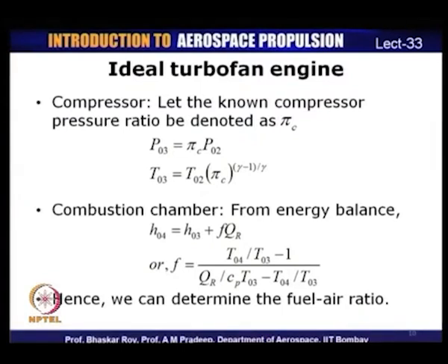And now, we move on to the combustion chamber. Combustion chamber analysis is something you are already familiar with; we did that in the turbojet. What we do is carry out an energy balance across the combustion chamber. At the inlet we have conditions of pressure and temperature coming from the compressor, then fuel is added in the combustion chamber and we find the exit conditions.